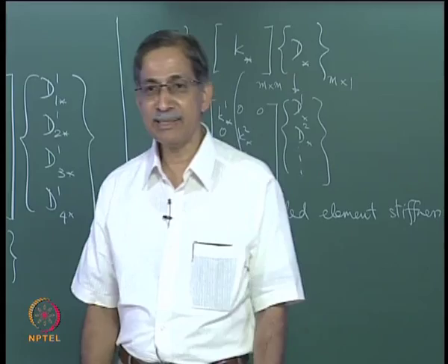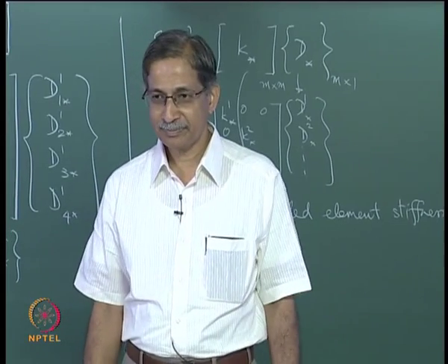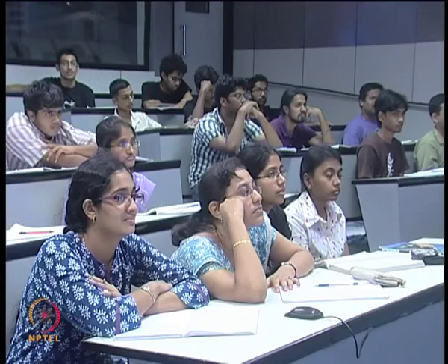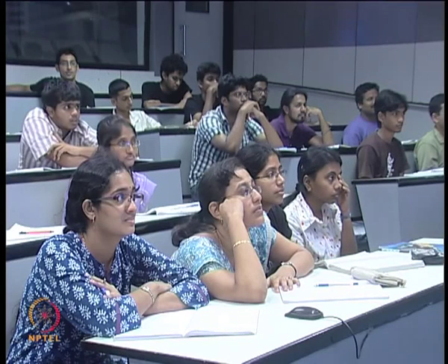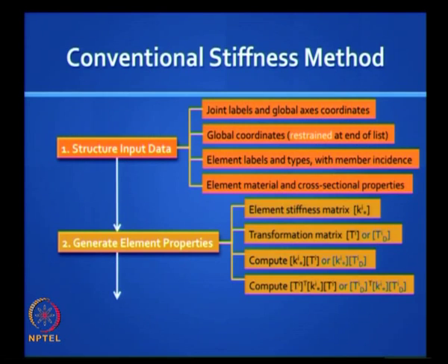Next step, what do you think is the next step after you've given the input? That comes much later. I mean, I am not saying what you have to give, you are right, you have to give the loads. What is going on inside? The moment you give this, it is not waiting for loads. It is trying to be ready to handle your loads. No? So by the time you key in the loads, it would have done its homework. What is the homework? It will generate the element properties, right. So we have done that, the element stiffness matrix, the transformation matrix.